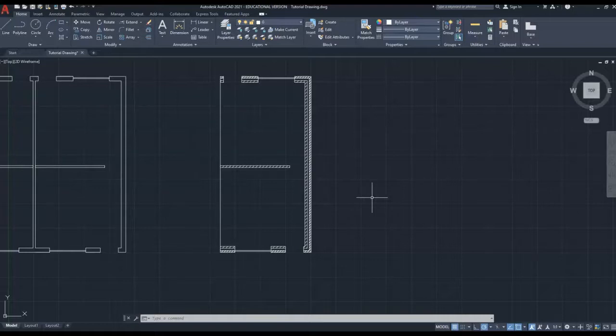And for those who understand construction drawings, you know that hatching denotes brickwork, and internally you know that denotes blockwork. And similarly for internal walls, I know now that that's definitely a solid block wall, but I might have other walls in there that are timber stud partition, and that would have a completely different hatching. Okay, so that's hatchings that we've covered, and I'm not going to do too much more on that, but I did say at the beginning that I'd show you some of the common errors.